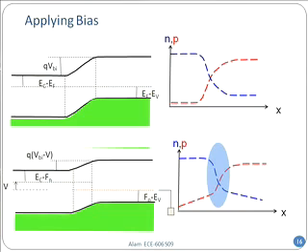But now I want to focus on the junction, because the junction is where recombination generation plays an important role. Why in the junction? When you diffuse a dopant into, let's say, a p-type material, in the junction region many times the dopant atoms do not find their chair, meaning they do not find the spot they should sit in. Therefore, the junction is always prone to a lot of defects, and processing is very important. So you primarily focus on the junction region where recombination generation might play an important role.